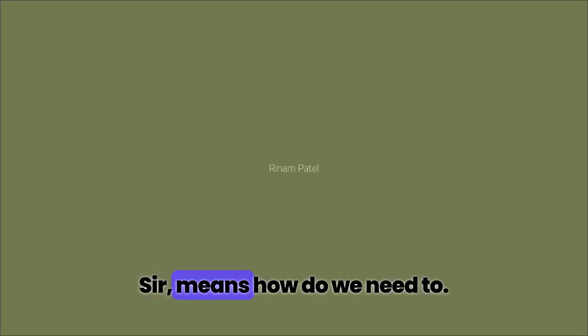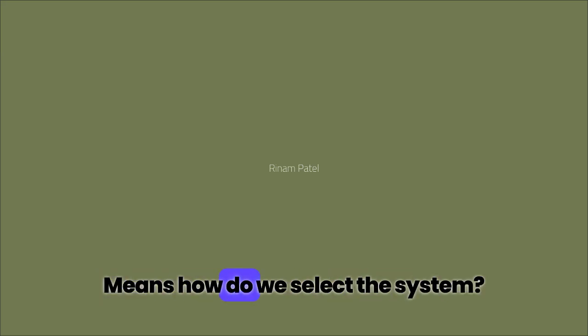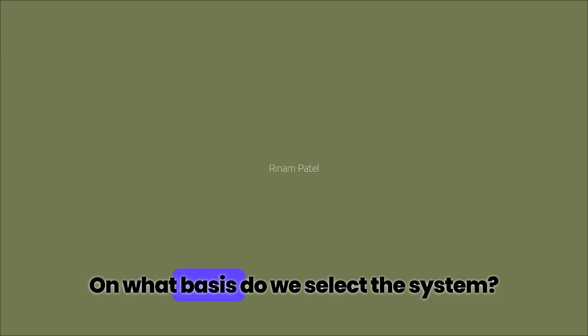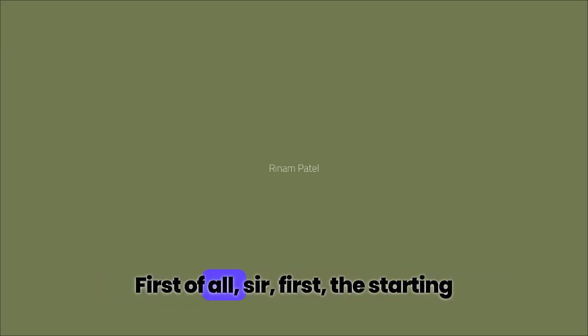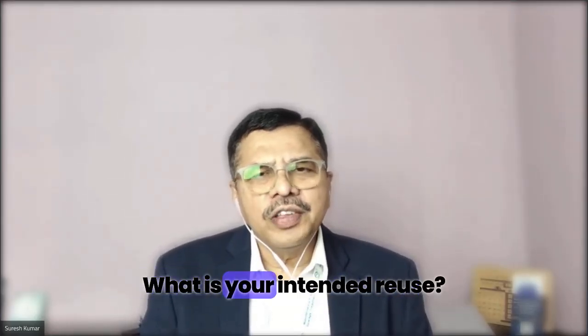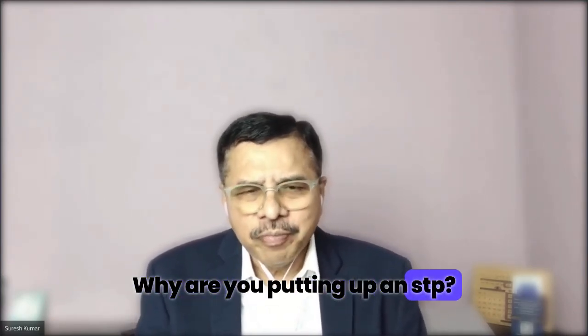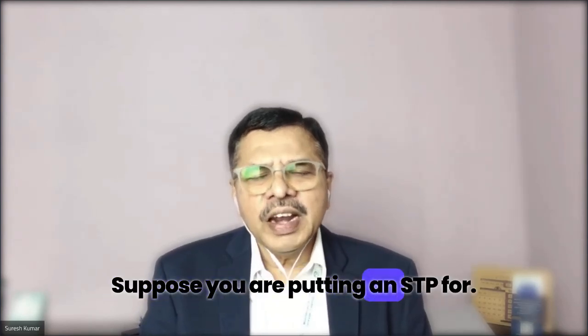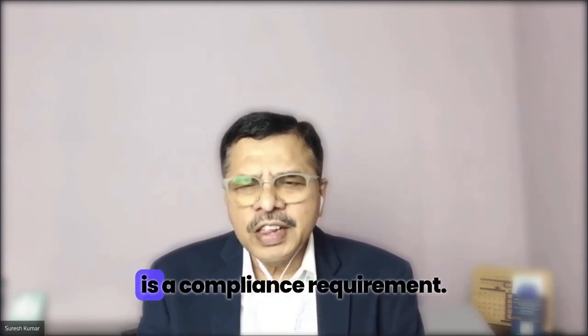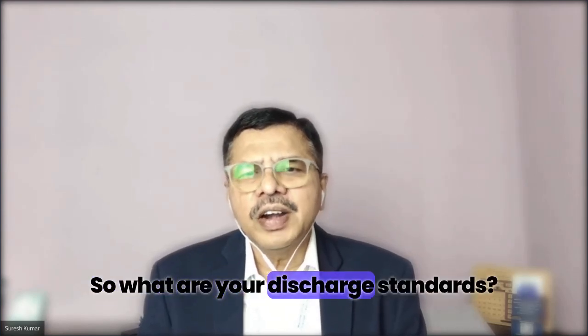Sir, how do we select the system, whether it is MBR or MBBR or SBR, on what basis do we select the system, first of all? Sir, the starting point for any STP selection is what is your intended reuse? Why are you putting up an STP, right? Suppose you are putting an STP primarily for meeting compliance requirements, which is most of the cases. So what are your discharge standards?